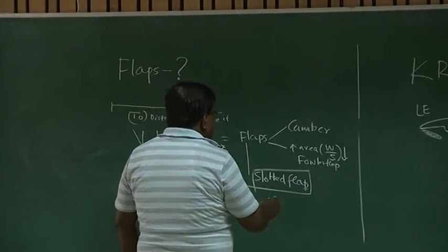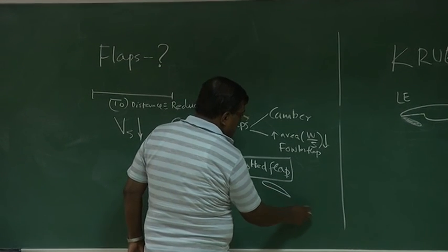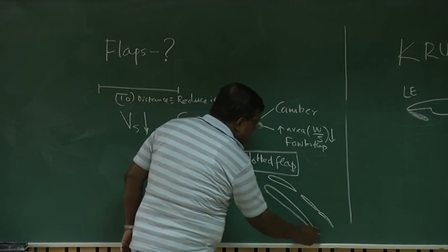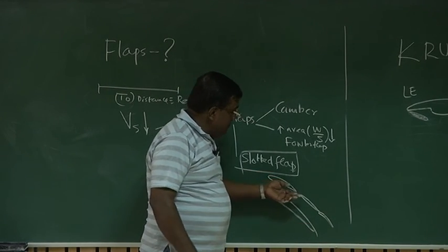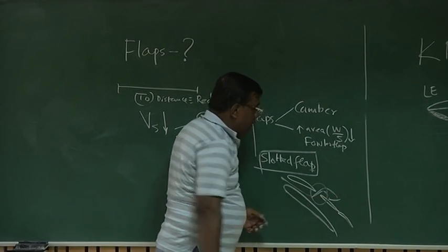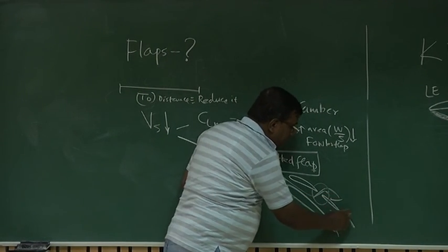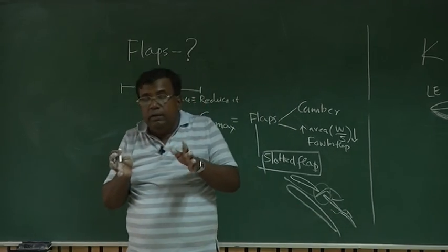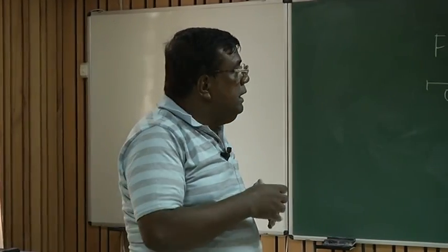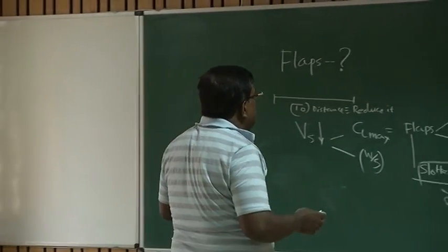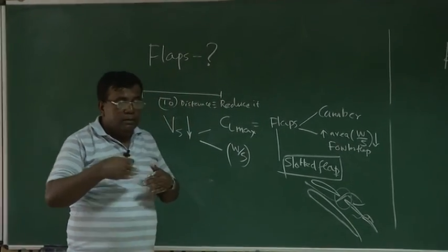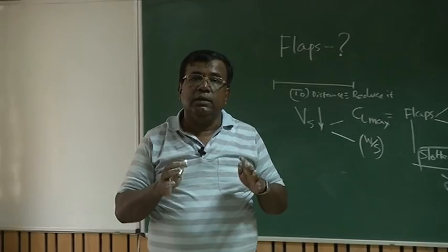And in that, we have put multi flaps like this instead of one flap with such a large angle, because I know this fluid coming from here will energize this, so its stall will be delayed. Similar things will happen here, and that way I can efficiently design multi-aerofoil flaps. And that is how we are trying to increase CLmax so that Vstall is reduced and we have a shorter takeoff distance. Thank you.